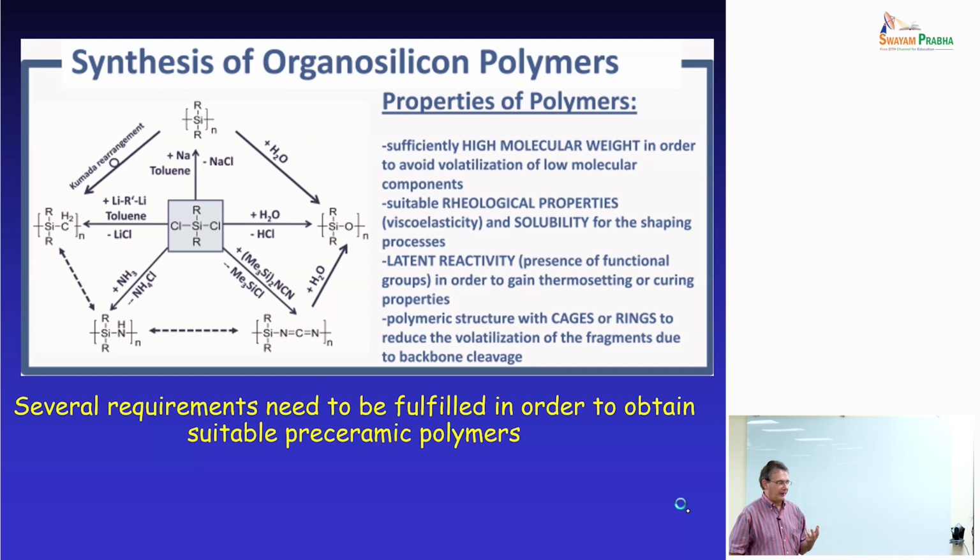So if you shape a thermoplastic polymer and then you heat it up, it loses its shape. So in order to avoid that, you need to embed into the preceramic polymer the possibility of cross-linking. So you need to use something that can be shaped as a thermoplastic polymer, but is able to behave like a thermoset polymer during pyrolysis. And not all commercially available materials, siloxanes, or preceramic polymers have this possibility. For instance, Yajima's polycarbosilane cannot cross-link, so you can make very nice fibers, but then if you try to pyrolyze them, they melt or they soften.